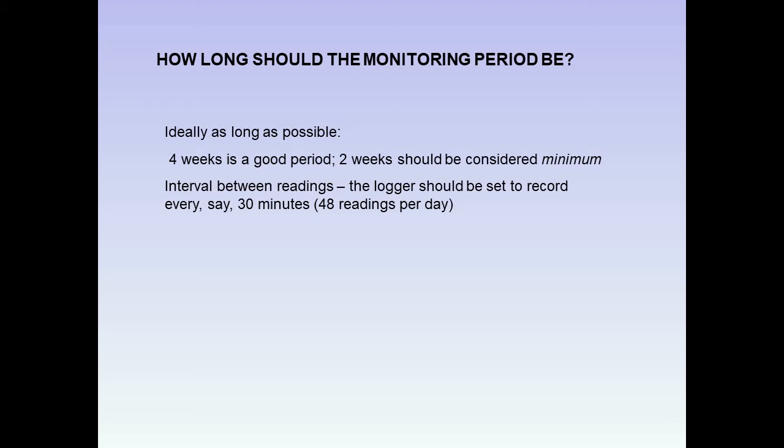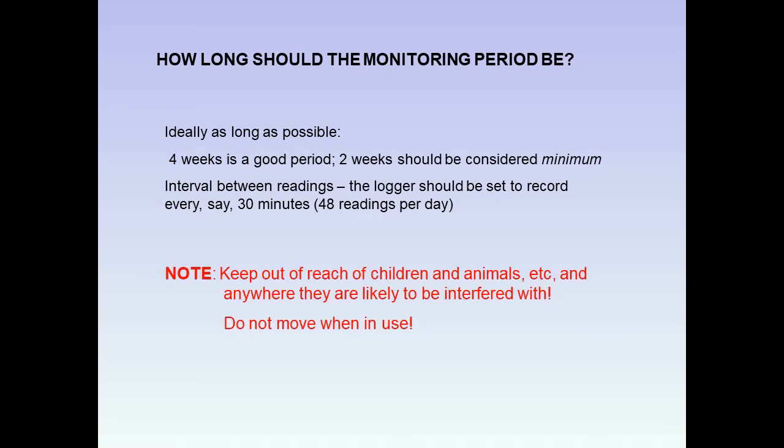How long should the monitoring period be? Ideally as long as possible. 4 weeks is a reasonable period. 2 weeks should be considered minimum. Interval between readings, well, about every 30 minutes. That would give us 48 readings per day.